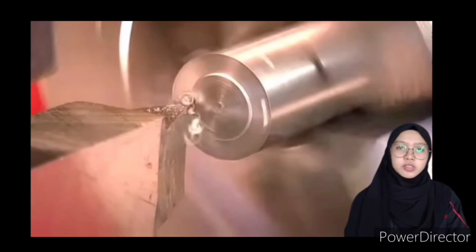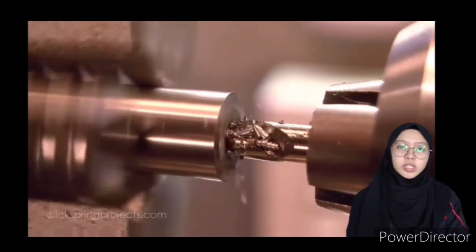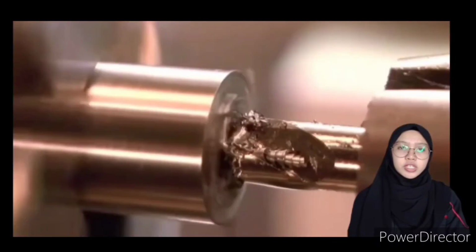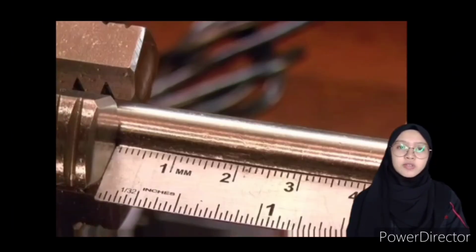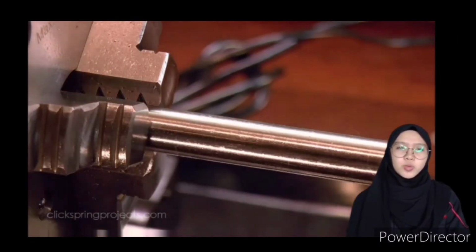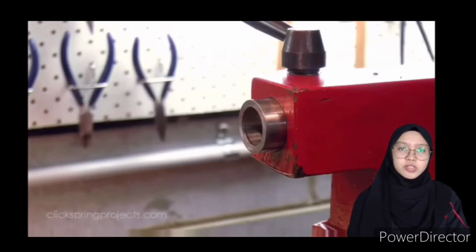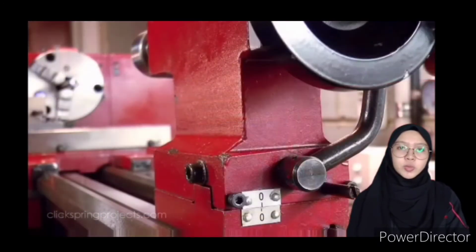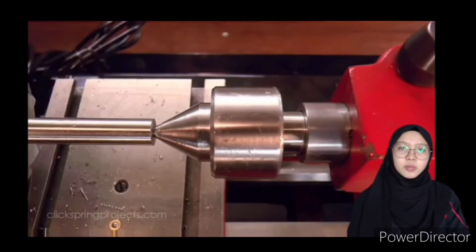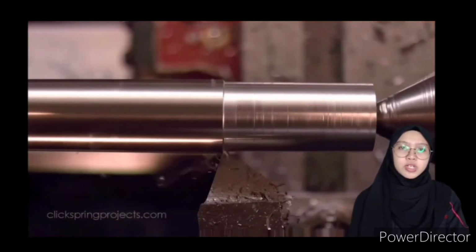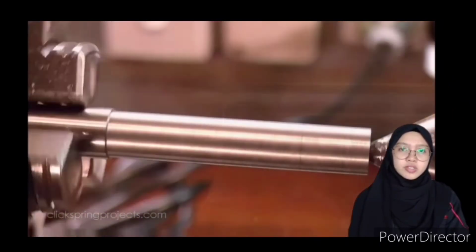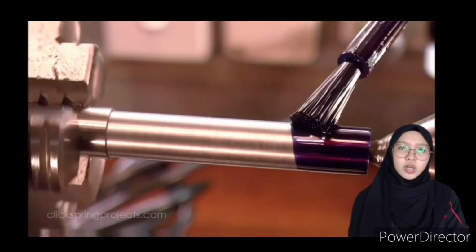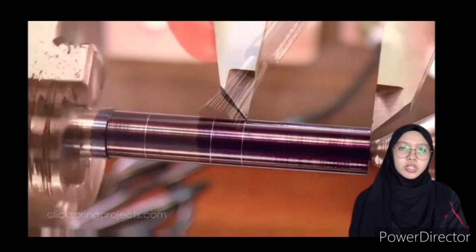It is 60 millimeters. After that, make a hole in the middle of the workpiece by drilling. Use the upright drill bit and drill just a little to simplify the work that needs to be done after this. Stop the lathe and remove part of the workpiece to a length of 55 millimeters. Place the lathe center point on the workpiece and then start the turning process. It is a process to cut the diameter of the unnecessary material. Using a layout solution, cut the area to be threaded.